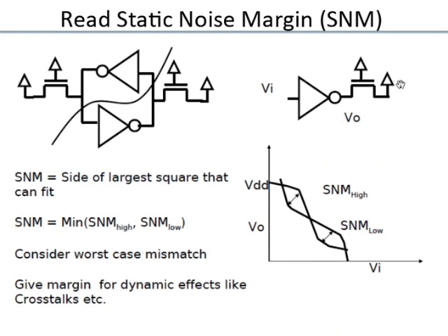Why? Because when Vi is high, this PMOS is off, of course, but then you have this in parallel. This access device is on. For the DC transfer curve analysis, basically what you have is the PMOS here is off, but this access is on. So this access device fights with the pull down driver device, and so the output voltage doesn't go all the way to ground. So now you have this curve out here for this half cell. Similarly you do the curve for the other half cell.